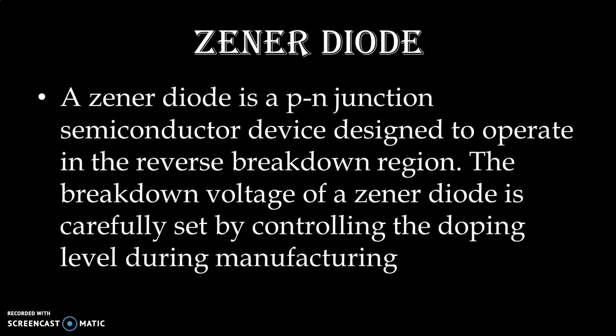In case of PN junction diode, when we apply reverse voltage, only leakage current flows. When we go on increasing the voltage in a reverse bias condition, at a certain point avalanche breakdown happens and very high current starts flowing through the diode, and in this condition mostly the diode will be damaged. But there is a difference between Zener diode and PN junction diode.